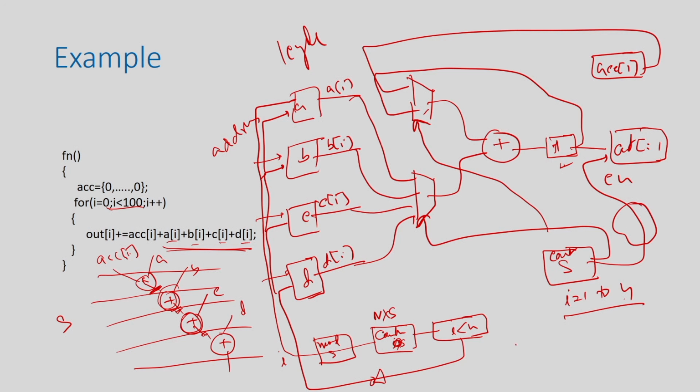So, this counter control thing we have to accurately design, but the overall idea of this counter control thing is that I will increase only to I plus 1 once this one iteration is over, right, S is done, and then I can actually take I 2 and again load it for 4 cycles. But the important factor is that although there are so many operations, and since I try to do this in say 4 cycles, I can actually execute these things using a single adder, right. So, basically the objective of this discussion is to emphasize that even if there are many operations and if I do a rolled implementation, my resource requirement is minimum.